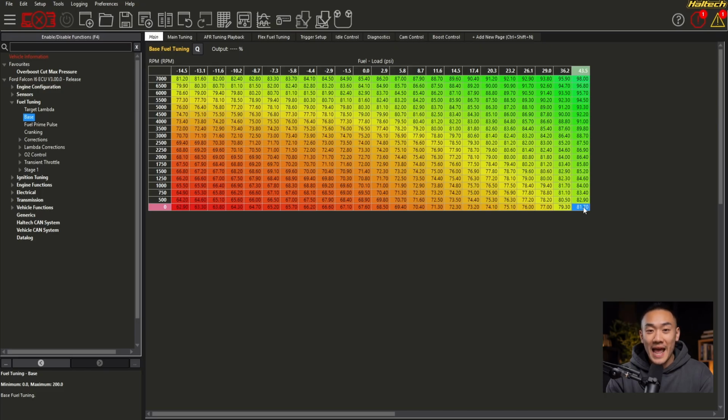This ties directly back to what we covered in the lambda video. If the stoichiometric ratio is wrong or the injector data is incorrect, the ECU calculates the wrong fuel mass. To compensate, VE numbers get pushed higher or lower until lambda looks correct. The engine runs fine, but the airflow model is no longer representative of reality. That's why VE should always be treated as an air model first and a tuning surface second. Once the airflow model makes sense, lambda control becomes easy, repeatable, and stable across conditions.